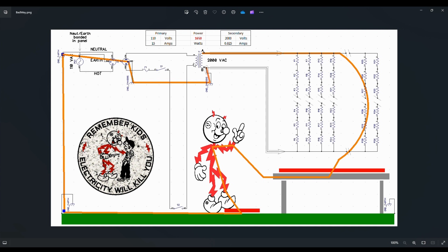However, when you take this transformer out of the microwave oven and you screw it down to a board, or you bolt it into a beautiful looking enclosure or something in between these two, this is no longer in its normal operating environment, and all bets are off. If you leave this connection in place, you have provided hundreds of ways, thousands of ways, every way that an electron can imagine, for terminal B now to try to attract electrons back through this current path.